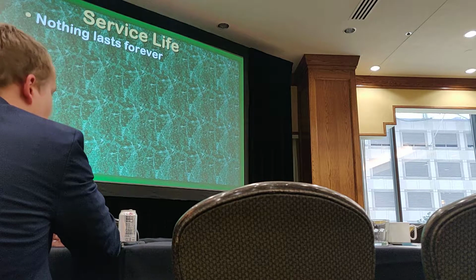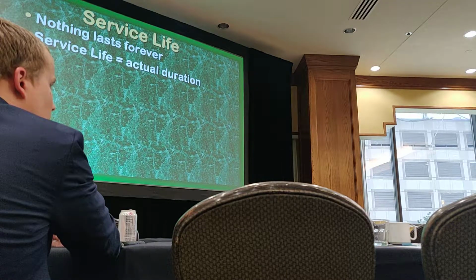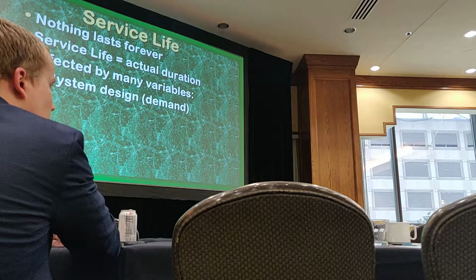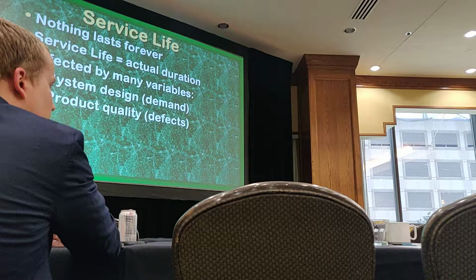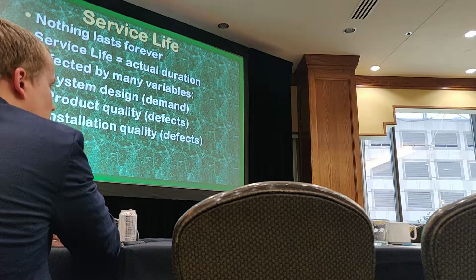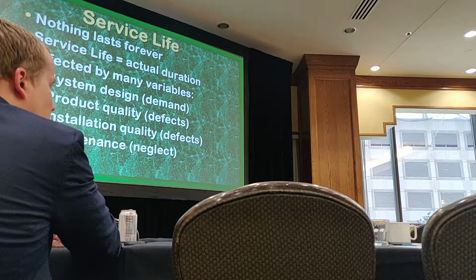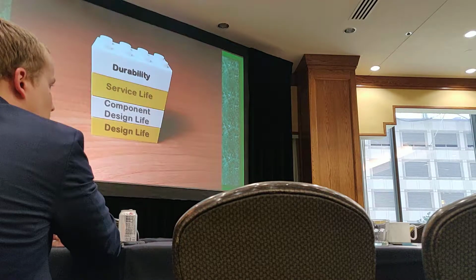So the service life is the actual duration of performance of the system selected. It's affected by many variables, including the system design or the demand that's placed on it, the product quality, or what we would call defects, the installation quality or construction defects, maintenance, or when it's deferred maintenance, we just call that neglect, and the climate and exposure. The same building in San Antonio is not going to last the same in Detroit. There is a difference based on exposure.